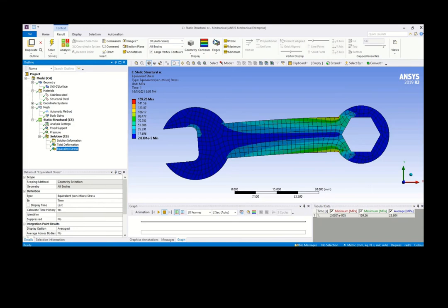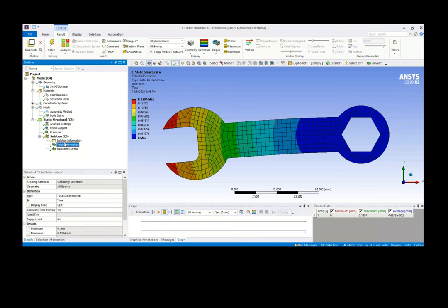So if you can compare it with the yield strength, then you can know whether it will fail or not. So we will move towards failure analysis. Once we know how to determine the deformations, I mean, solving the solid mechanics problems, here we're talking about the deformations. We get the U1, V1, U2, V2, U3, V3, all this information from the stiffness matrix and the load matrix, and we can solve for U.